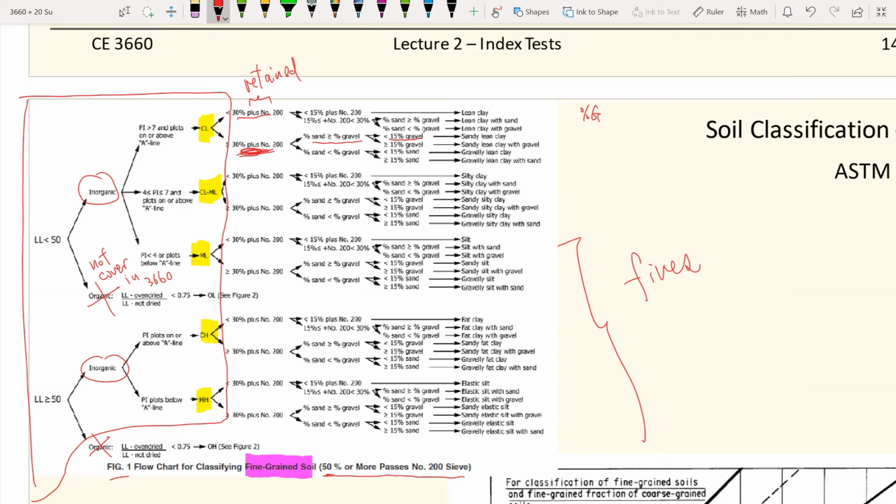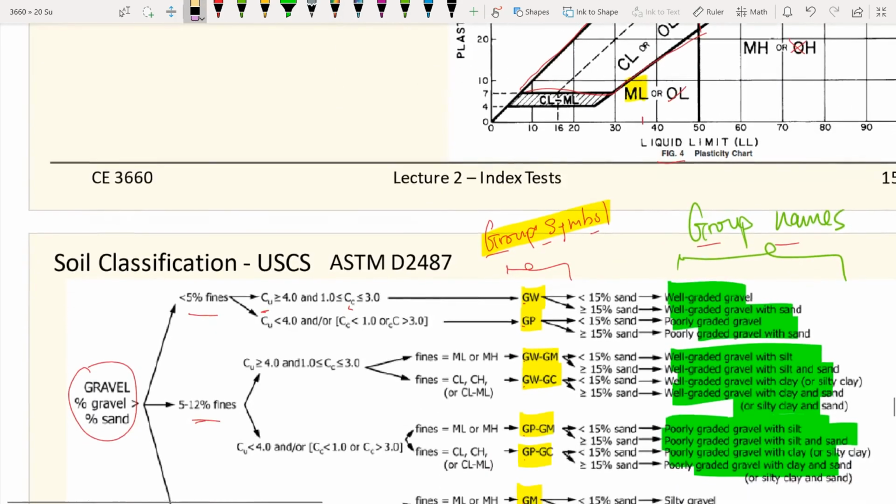let's put it down. Percent gravel for example number 1 is 2%. Percent fines is 50%. So this is example number 1. Percent sand is 48%. Since we have 50% fines, this is greater than, this is 50, not 5. Just make it clear. So this is 50.